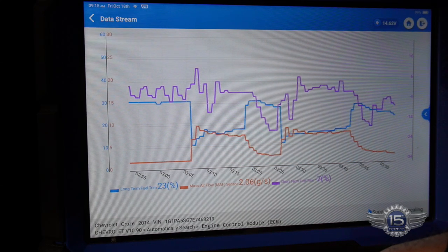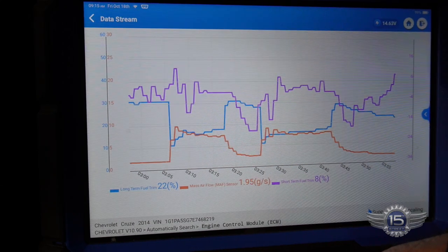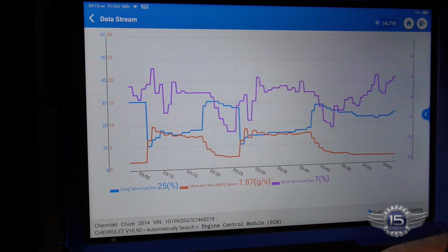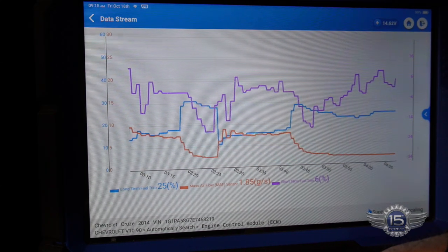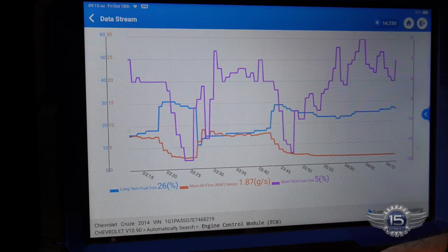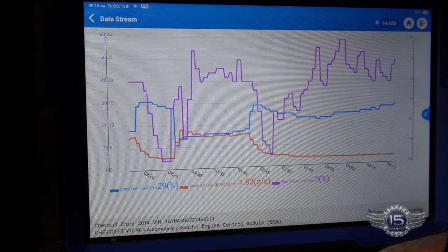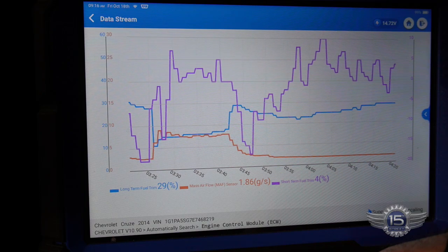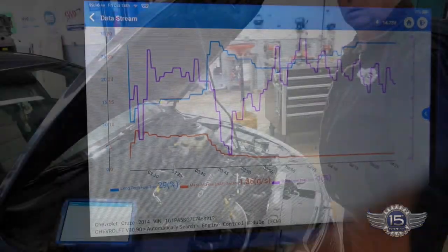So let's check it for vacuum leaks. Make sure the purge valve isn't leaking. Those are pretty common on these. You can unplug that purge valve, and with it electrically unplugged, it shouldn't allow any air to pass through. So let's check the purge valve, and check for vacuum leaks. We'll smoke it, see if there are any vacuum leaks, see where that gets us and go from there.